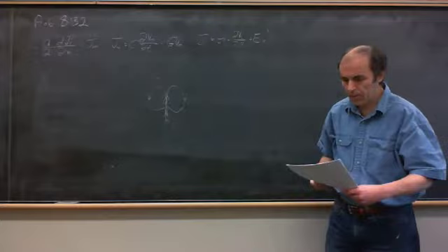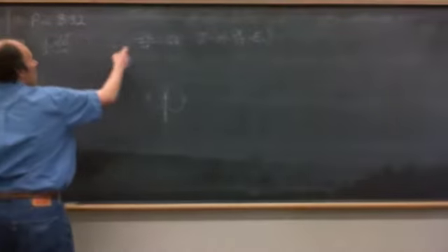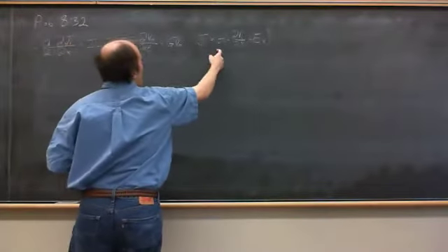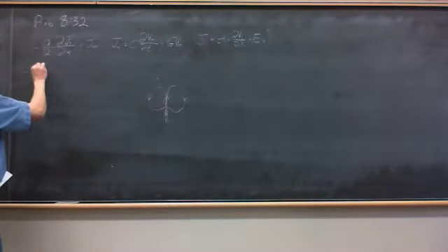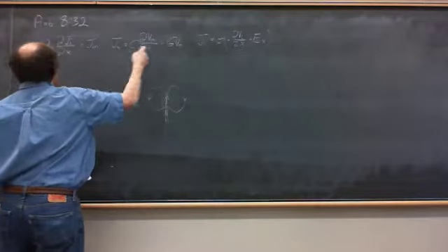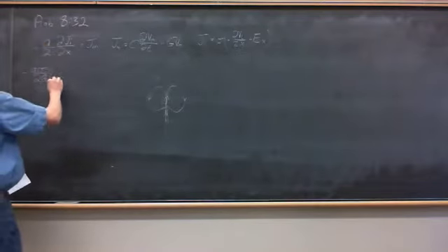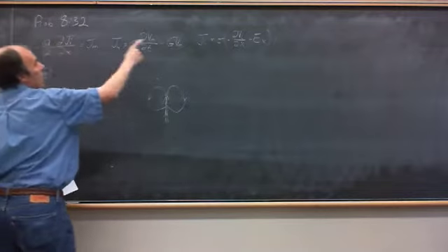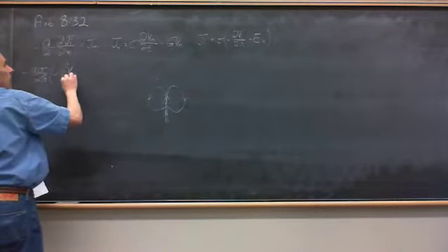Then we're going to put these three together, and we're going to put this for Jm, and for Ji, we're going to put all that. So what do we get? We get a minus a sigma over 2. I'm also going to divide through by G, because we've done this before, so I'm not going to do every step. And you're going to get a derivative of a derivative, so minus d squared V dx squared.